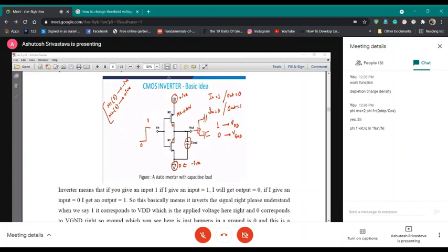If one transistor has a subthreshold current of nanoamperes or picoamperes, then the whole unit having 10 to power 9 to 10 to power 12 transistors would scale up the overall leakage current from nanoamperes or picoamperes to amperes, because each transistor contributes to the subthreshold leakage.